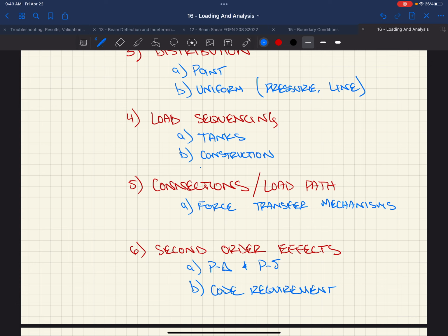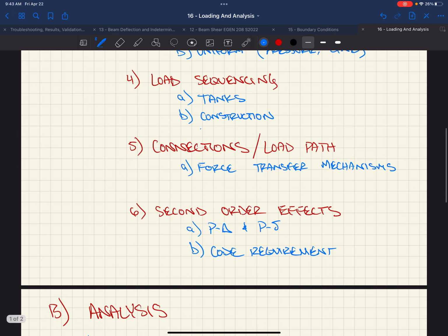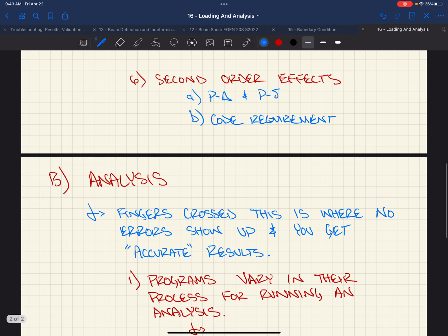So I'll just tell you that the seismic manual requires you to do certain analysis with respect to forces on brace frames. When you're designing the columns for them, you might have a model in which all of the braces can only hold forces in tension and none in compression and stuff like that. So there's code requirements that require us to do stuff.